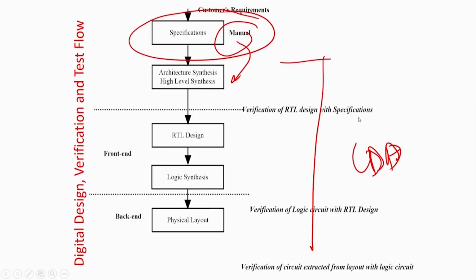Let me now come to an example of optimization. This part, when I am telling you about manual, the customer requires high level diagrams, that you require an adder, a ripple carry adder or multiplier or subtractor. This is an art. Given a problem to solve, what is the minimum number of circuits required to solve it in a reasonable amount of time? Say for example, for some operation I require 20 adders to do it. But say that I have a lot of time because I do not require that amount of speed. So you can use 5 adders and use them in 2 steps to solve the problem. But if you want a super fast design, then you have to have 10 parallel adders. So this part is fully manual, or very little CAD can come in there.